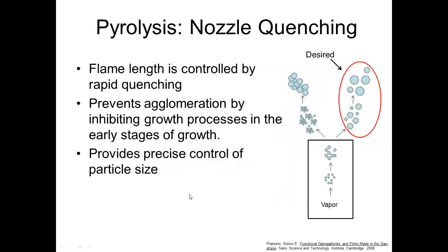So this shows us that flame length controls the particle that we want. A goal we would aspire to is to take the flame and truncate it halfway through or so, and that's going to give us the most robust particles, because the particles formed in the latter part of the flame are the ones that are agglomerated and rather mechanically loose.